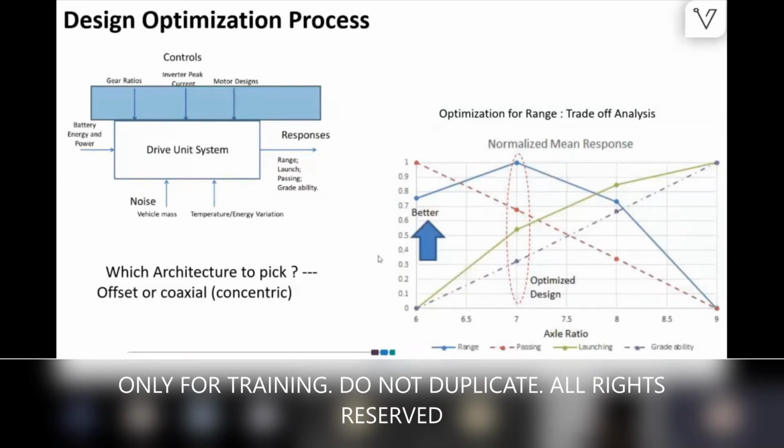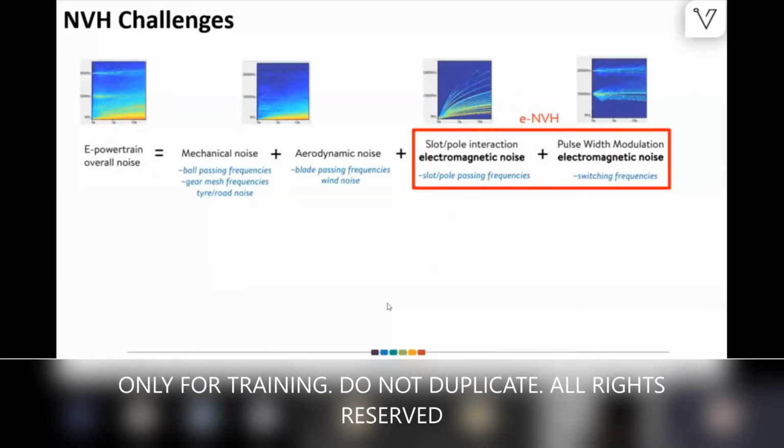And then another element to this is vibration, because when you put the rotor slots, gearing, and all these together, they also have some interaction, modal analysis. They have their own natural frequencies, and then their own harmonics. All of these will have an impact on noise and vibration again. So what housing we have. When we talk about complete noise or vibration analysis, we have to consider all of these vibrations.